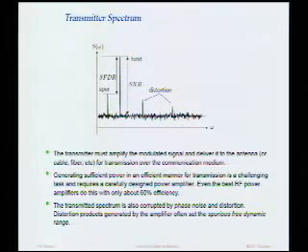Okay, I'll use the mic. They may be in somebody else's channel and now we're causing interference? Exactly. If we want to be good users of the spectrum, on the receive side, we have to be good users on the transmit side as well. So we basically want to transmit information in the bandwidth that we've been allocated, and we want to transmit as little junk outside of that bandwidth as possible.